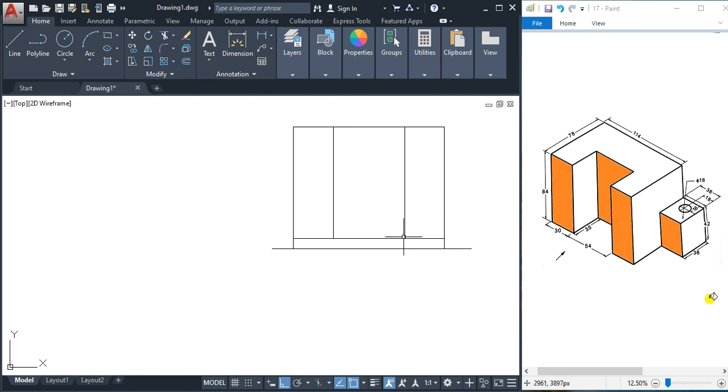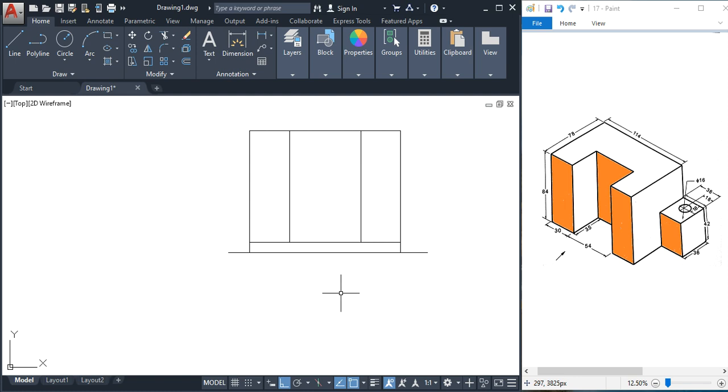And we have to represent this one, so this is given 36 and height is 42. This line will get combined with this one, a continuation. So you can draw a line of 36 here from this point. So this is 36 we have drawn, and height 42 given. If you see, this is 42, and here you can draw a line parallel to the reference line or base.